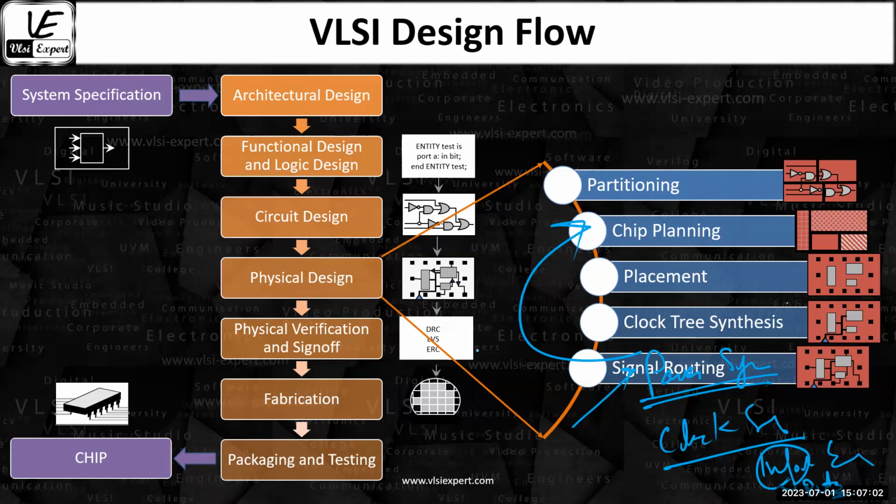So these are basically the stages. Always remember, we do first power planning, second clock planning, third data signal planning. And stage-wise also it will come in that particular way. So when you are doing the partitioning, at that time we will say, okay, I'm placing the block here. So power planning. Then where exactly I'm going to place the standard cell. After that, only after that you're going to connect the clocks. Then the third thing, whatever the remaining space is, we'll do the data signal.